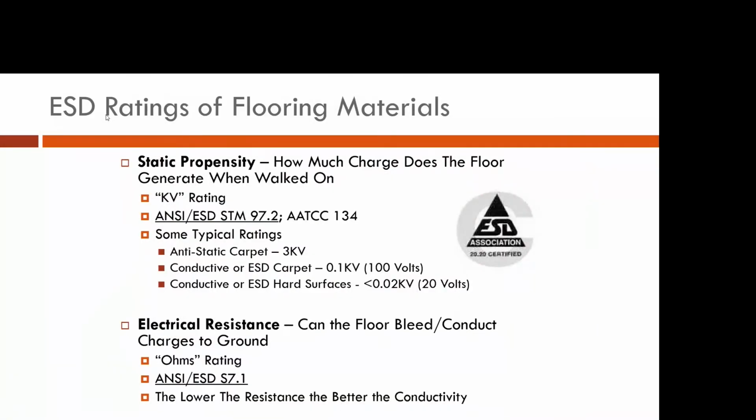The other rating we're going to take a look at is the electrical resistance. This is done with really two test methods. Resistance from point to point, so that's from a point on one floor to another point on the floor. And then also, does the floor have a path to ground?